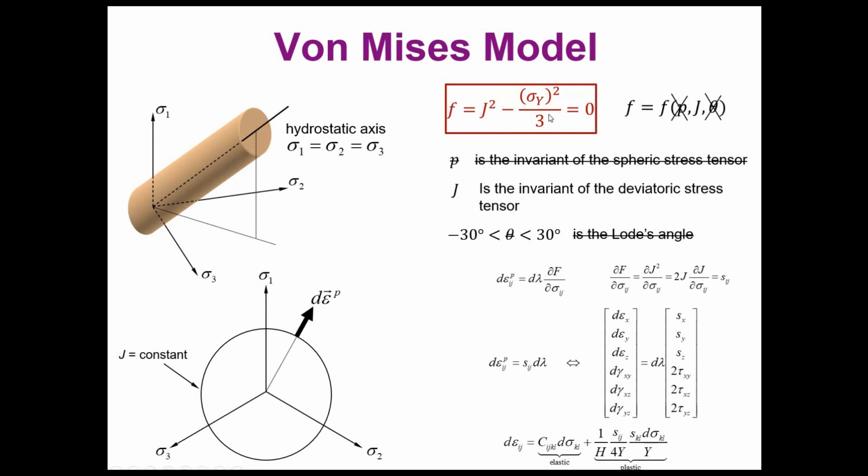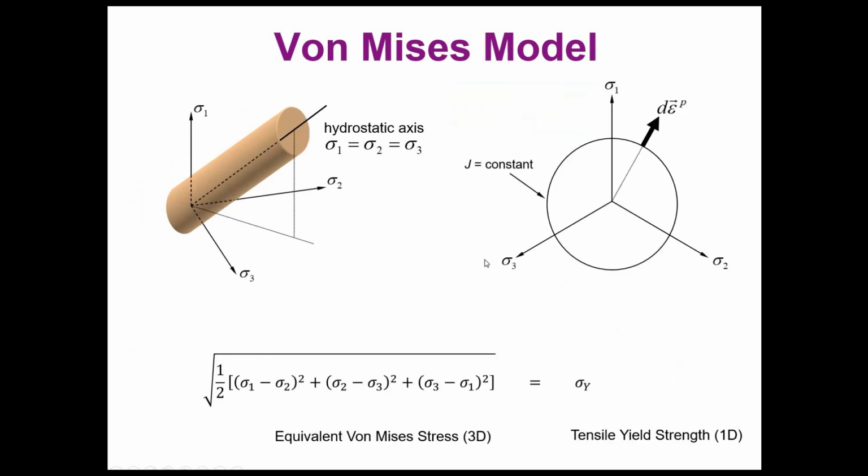But in this equation in here, you see that we have included the elastic yield strength, or this could be the plastic if we are including hardening. But the thing is, in your model, you can easily show in the post-process the equivalent von Mises stress, and you can compare with the value you know, because you have to define this value in your linear elastic model or in your linear elastoplastic model.